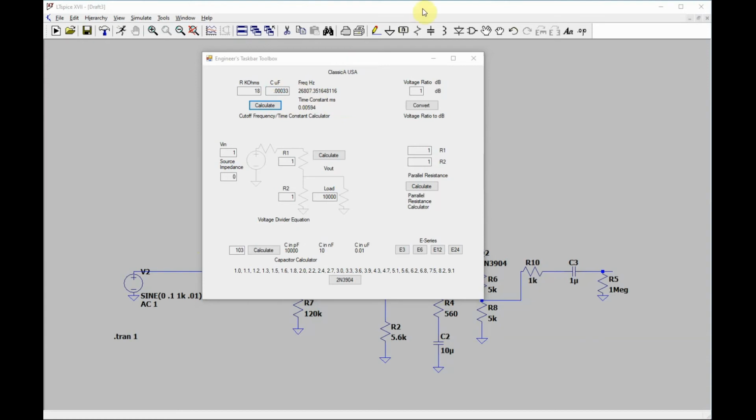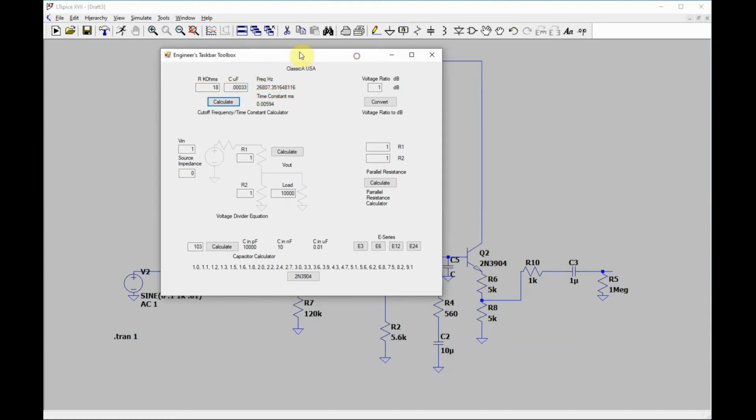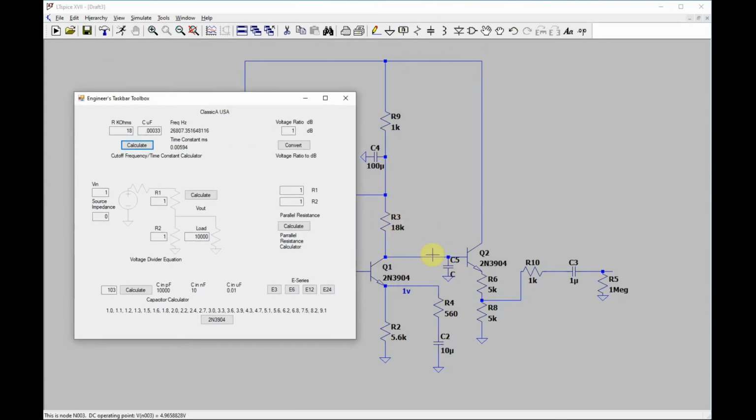Okay, sorry about that. So you've got 18K there, and this capacitor. If you want a little bit of a treble roll off, you can do that by putting a little capacitor across here. I figured it out for 18K, which is the source output impedance. It's like having one in series with here. That can roll off some of those highs that may end up oscillating, or you can just use it as a filter. I've done that before.